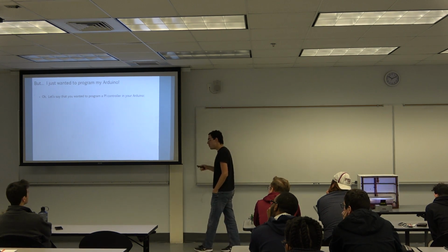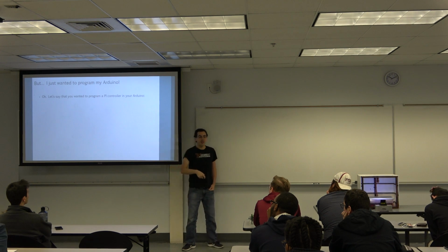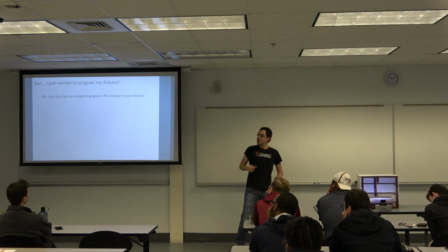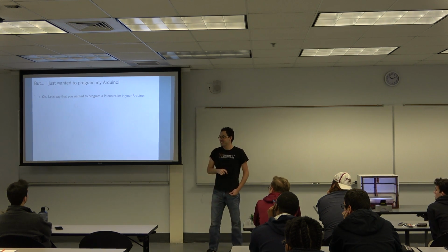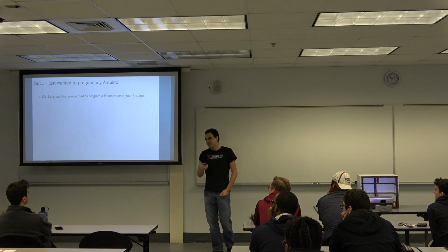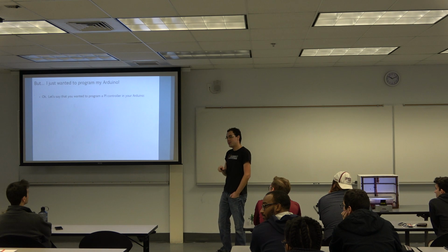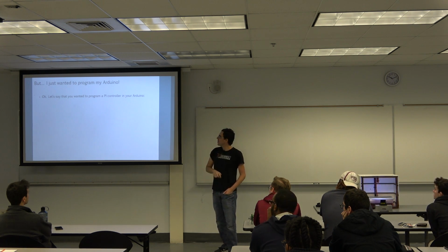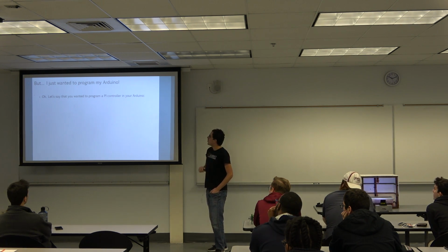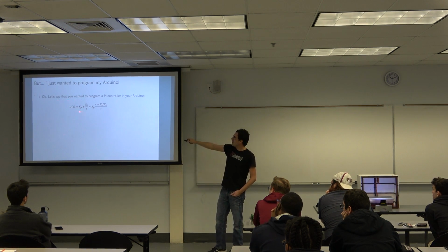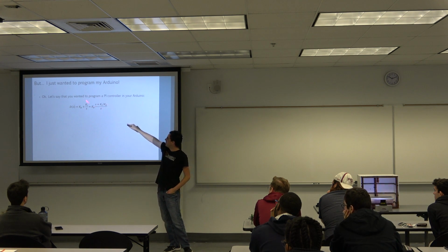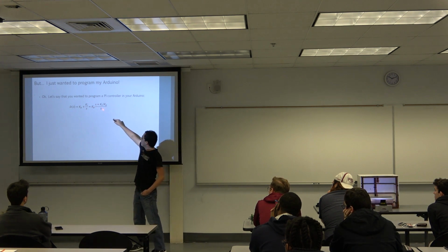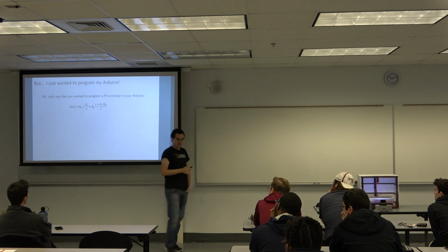So if I were to ask you, what is the definition of the PI controller in the S domain? What is the transfer function of the PI controller? KP plus KI over S. Exactly. That's pretty good. So D of S is KP plus KI over S. I do a little bit of math, just shuffling around to expose the pole and the zero.